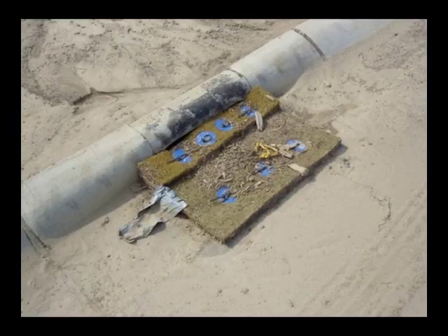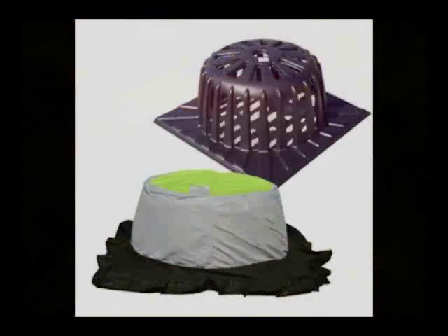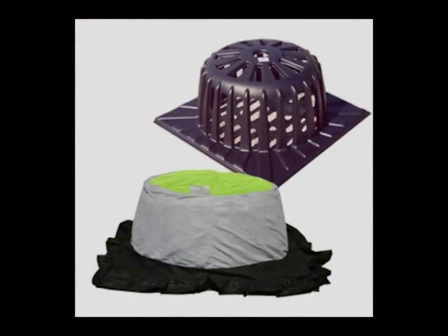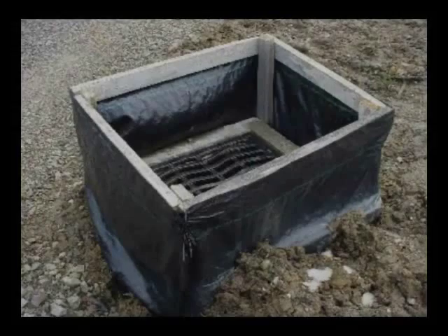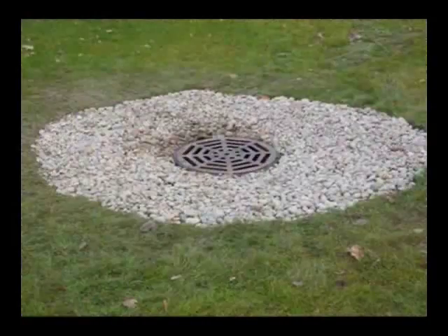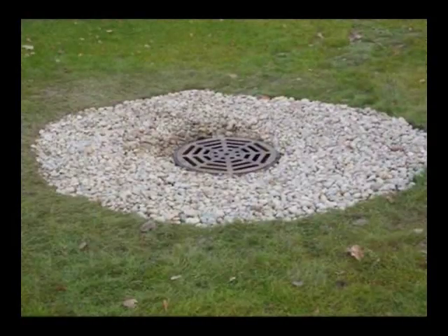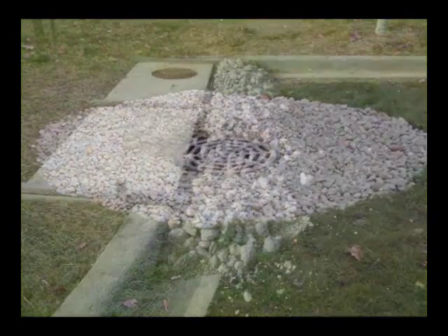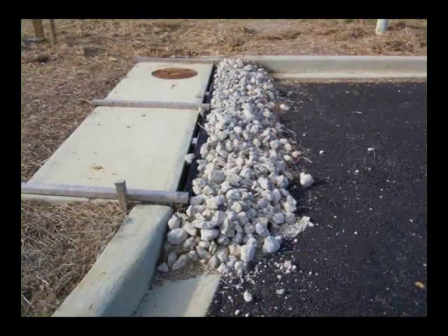They will quickly become clogged and cease to function. Yard drains can be protected by using products that consist of an elevated frame covered with filter fabric. Another method of inlet protection is properly installing silt barriers around the perimeter of the drain inlet. Finally, a filter made of coarse gravel or pea stone may be placed in front of or around the drain inlet. The gravel provides a certain amount of filtering action and is highly resistant to erosion.